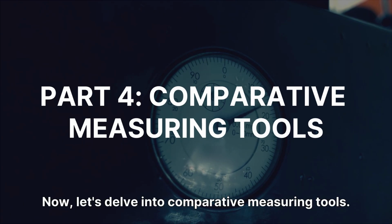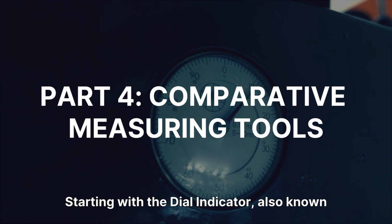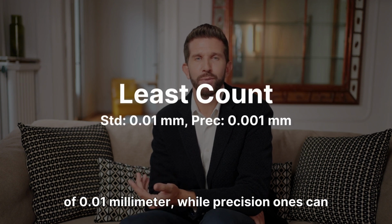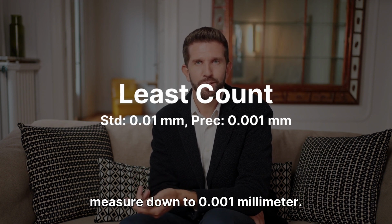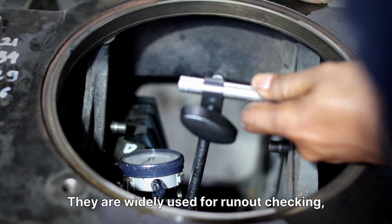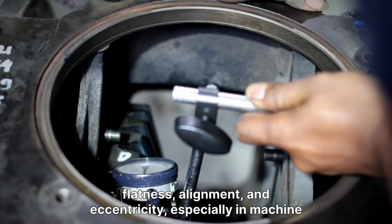Now, let's delve into comparative measuring tools, starting with the dial indicator, also known as a dial gauge. Standard dial indicators have a least count of 0.01 millimeter, while precision ones can measure down to 0.001 millimeter. They are widely used for runout checking, flatness, alignment, and eccentricity, especially in machine alignment.